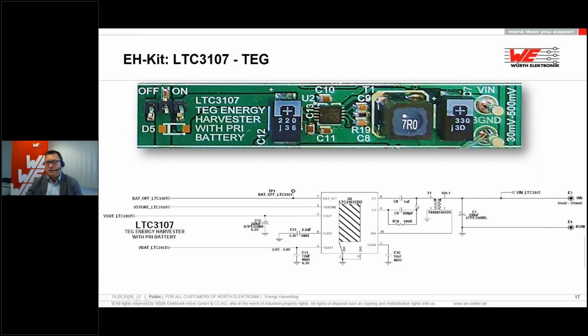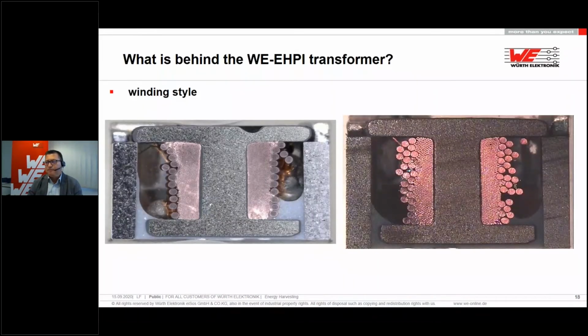As soon as the self-powering is reached, it has an output for a capacitor. After the capacitor is charged, this is its backup where it gets the power from, and then it starts to deliver the output voltage. So first feed yourself and then give to somebody else, and that makes the chip run by itself. It's very clever, and it's a very nice design. It's also very efficient, up to 97% efficiency, of course at low voltage. And we talk about voltage input to voltage output, not thermal efficiency to electricity. But this is cool stuff, and the coil is quite simple, maybe not that simple.